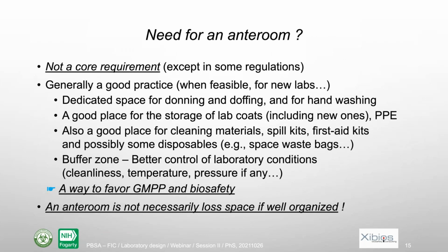Another way to increase separation is to have an anteroom. It's clearly not a core requirement, except in some regulations, but it is generally a good practice. For instance, for new labs, if you still have to build a lab, in that case, you could opt for that solution. Personally, I am really favorable to an anteroom. Why? Because it's a dedicated space for donning and doffing. So we will not do that either in the corridor or in the lab. You will do that in a specific place.